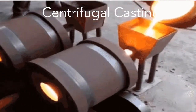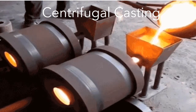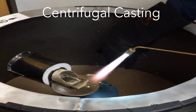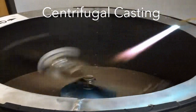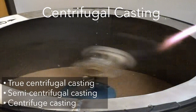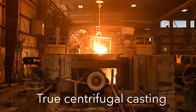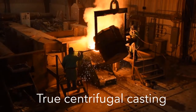Centrifugal casting is an ideal process to make seamless pipes and cylindrical shapes. The process is done by introducing the molten metal into a high-speed spinning mold. Sound metal will solidify into cylindrical shapes under the high pressure due to the centrifugal force. Centrifugal casting can be classified into three main groups: true centrifugal casting, semi-centrifugal casting, and centrifuge casting. In true centrifugal casting, the molten metal is poured into the rotating mold to produce tubular parts such as pipes, tubes, and rings.